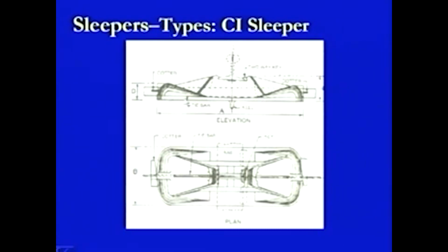And then in this case again we are using the tie bars, and these tie bars are jointed to these triangular plates by using cotters at this location or at this location. So, these are the type of sleepers which have been used, and probably you have also seen these types of sleepers being provided. There is a very thin bar which is used so as to connect this sleeper with the other sleeper on the other side of the railway track, that is based on the gauge.